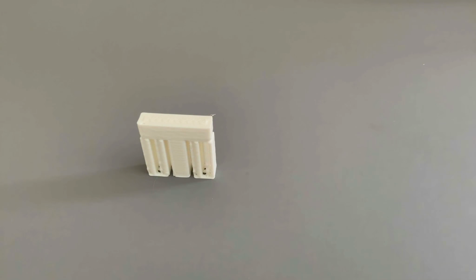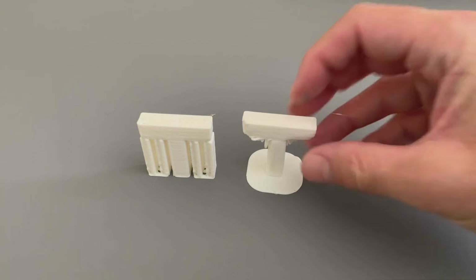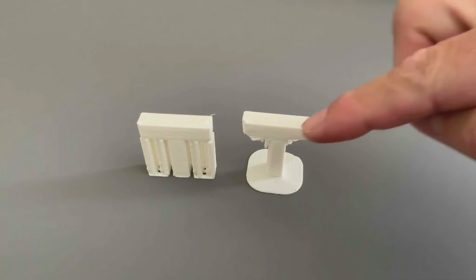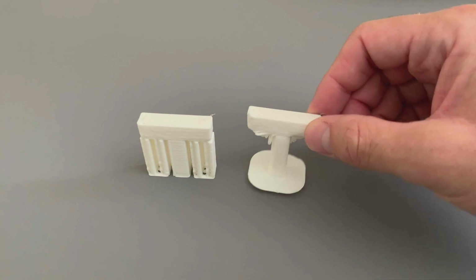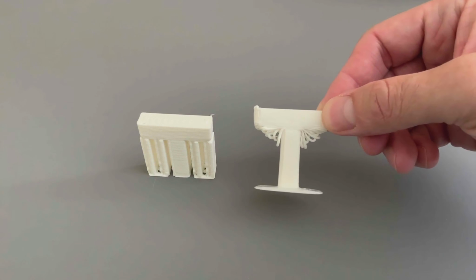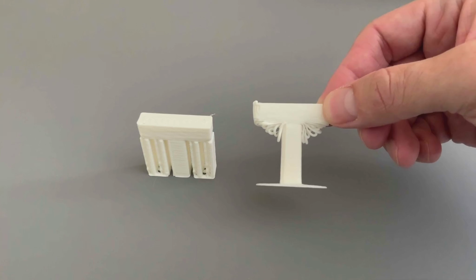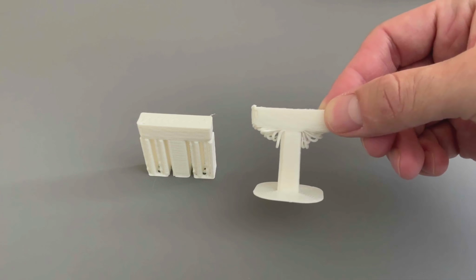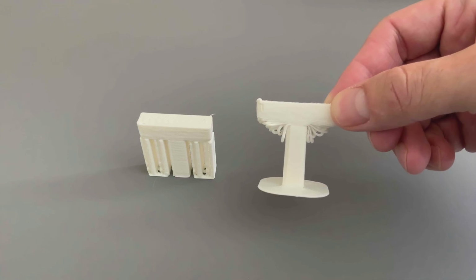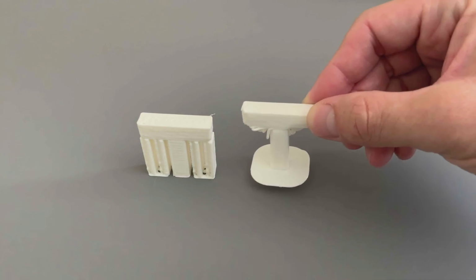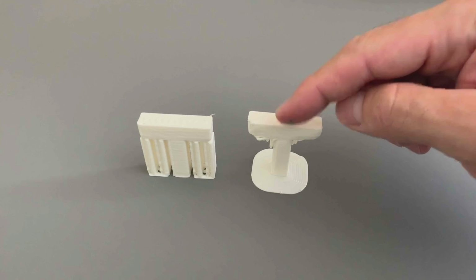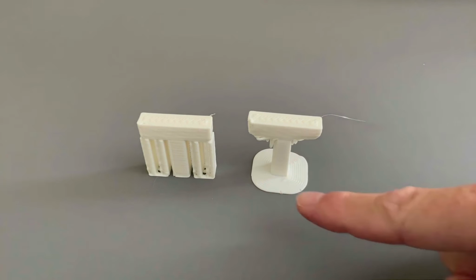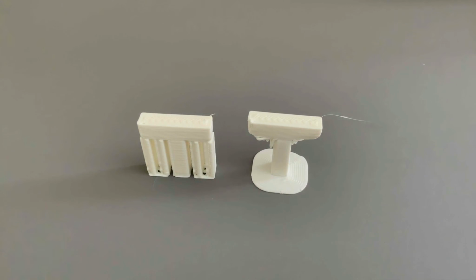And here is the T without the support. The top both look very good, but when I rotate it, you can see how the plastic had no support to sit on and it just moved down. And over time the printer was able to put enough plastic down horizontally to make sure the top worked well. When we started looking at the support, I also made a connection to the build plate adhesion.